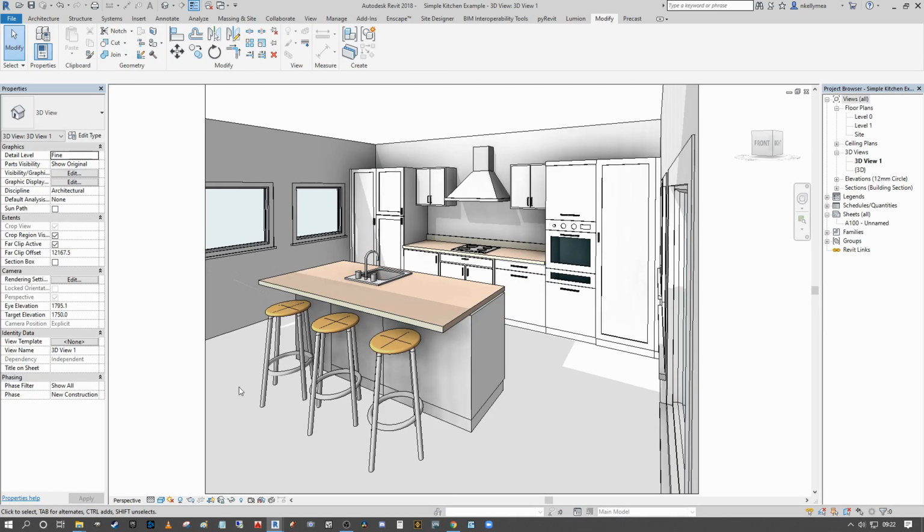So I highly recommend that if you're starting to model in Revit and you're trying to do your first kitchen, start with the default family so you understand how well the families can function. And then if you want to go and find something a little bit flashier on some of the external family utilities, you can do that afterwards, but at least familiarize yourself with the workflow.